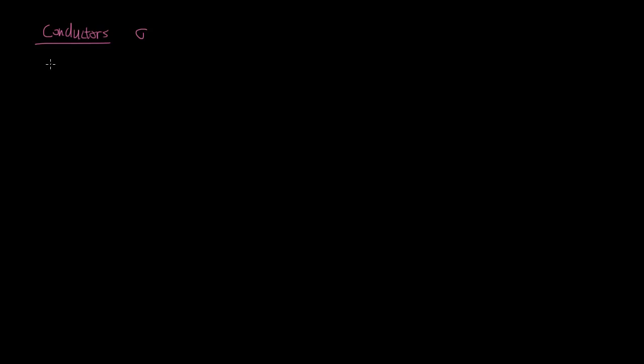So if we assume that sigma is large, then let's go back to our general expression of jk and see what that does. Remember, we started looking into lossy media by saying that instead of k being a real number, jk can be a complex number, so alpha plus j beta, where in a lossless situation, alpha is going to be equal to 0.